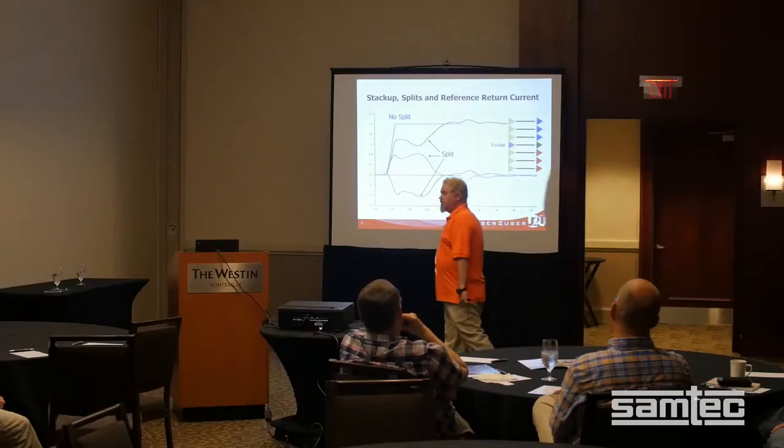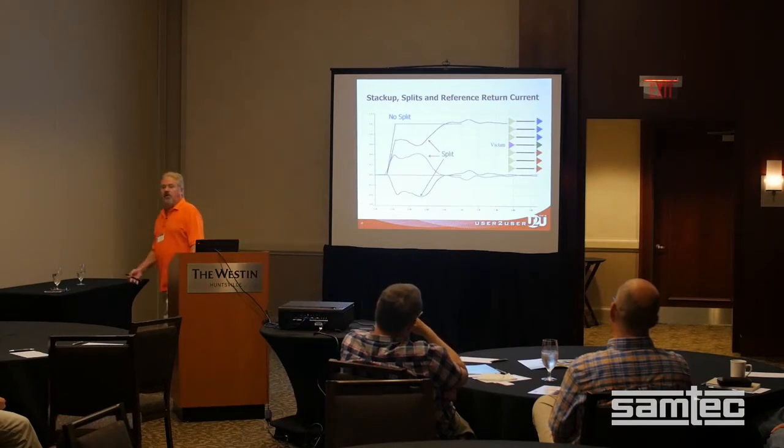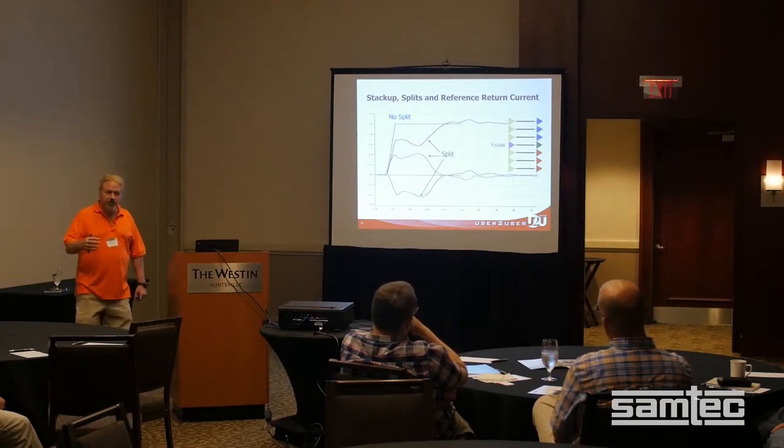A lot of people don't think about that when they lay the board out, especially if you design engineers don't give them rules. How do they know what layer? So you need to give them rules for what layer to use? No, I don't care what layer to use. I care what reference you're doing your signals to. Is it a ground reference signal? Is it a power reference?